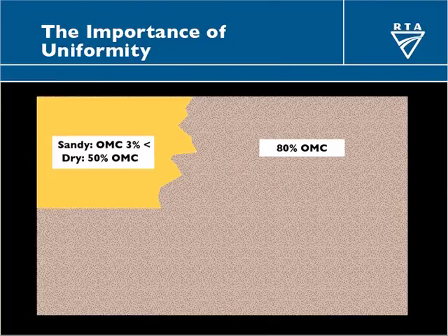If your compaction routine's set up for the bulk of the lot, what's going to happen there? It's almost certainly not going to be the optimum routine for it. And even if it is, and you're lucky, the fact that it's so much drier means you won't get the same compaction. It will definitely come up short.